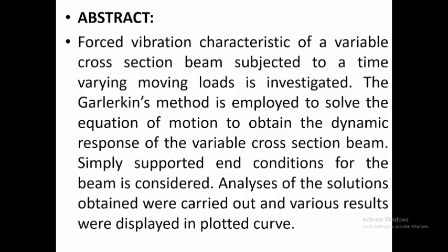Forced vibration of a variable cross-section beam subjected to a time varying moving load is investigated. The Galerkin method is employed to solve the equation of motion to obtain the dynamic response of the variable cross-section beam. Simply supported end condition for the beam is considered here. Analysis of the solutions obtained was carried out and various results were displayed in plotted curves.